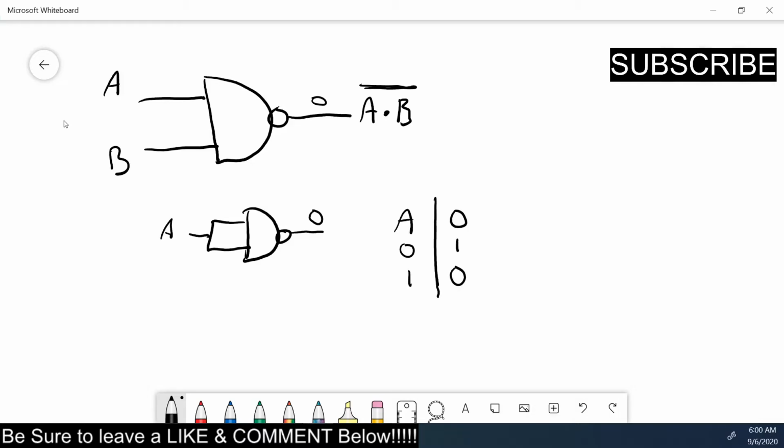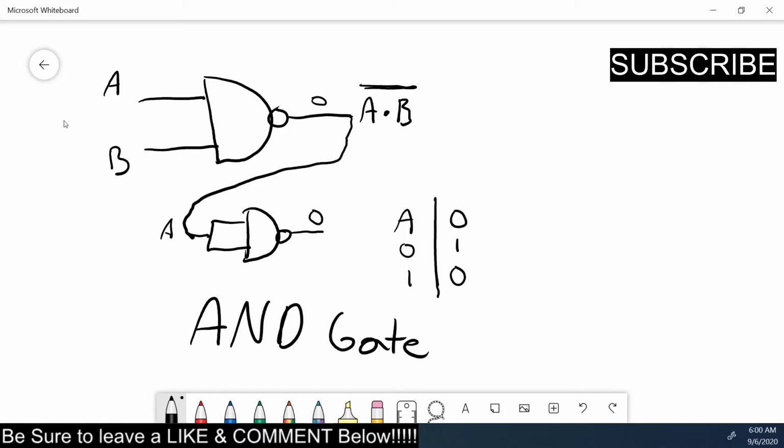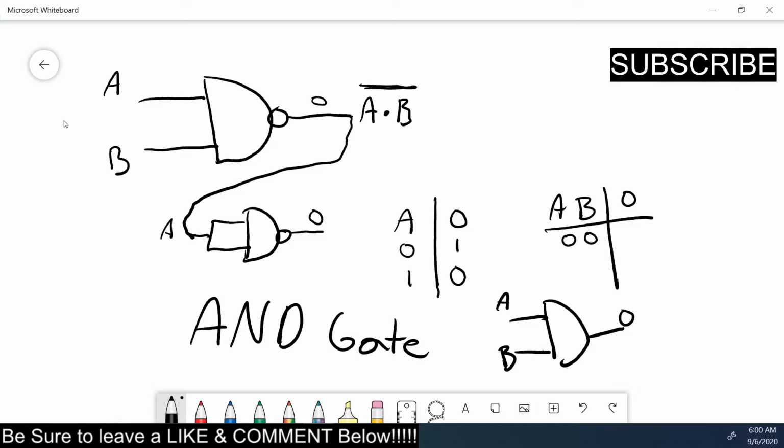So 2 NAND gates will make me an inverter. So if I take this output signal from here and plug it into 2 NAND gates, I will have an AND gate. And this is where combining logic comes in. An AND gate truth table looks like this: A, B, and output. If both are 0, it's 0; 0, 1 gives 0; 1, 0 gives 0; and 1, 1 gives 1. So it's pretty much the opposite of a NAND gate.